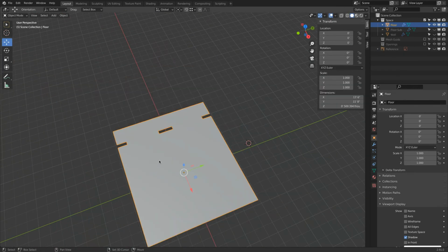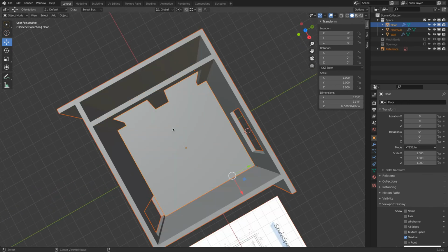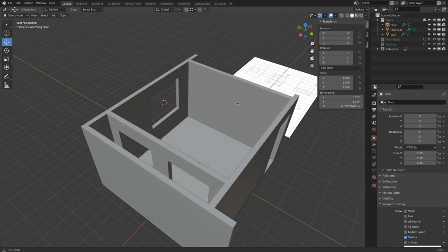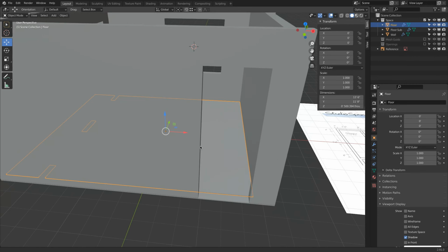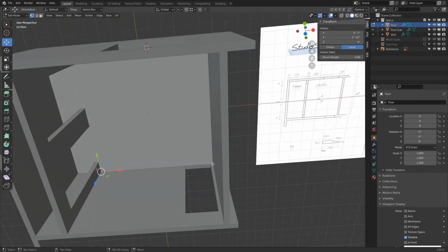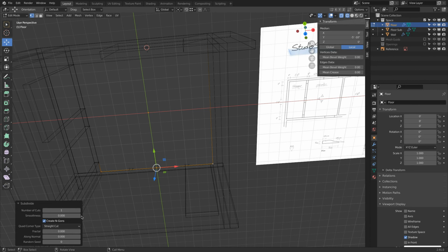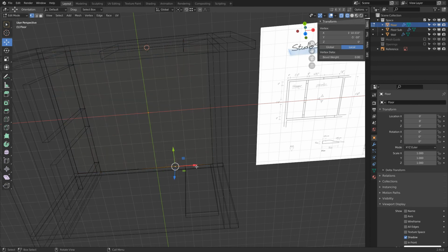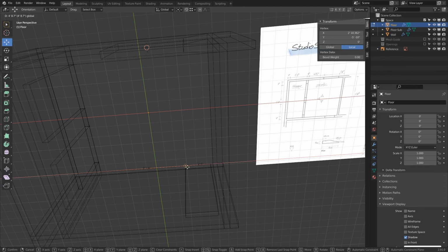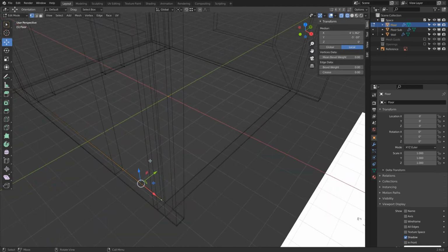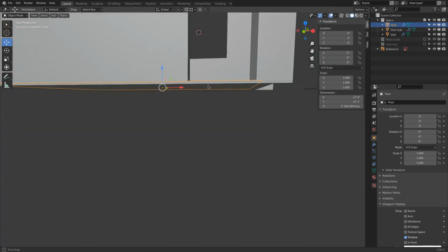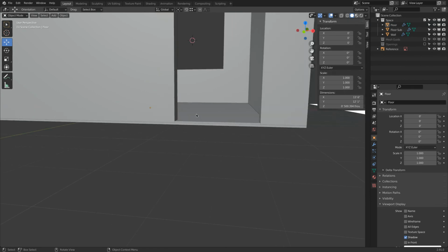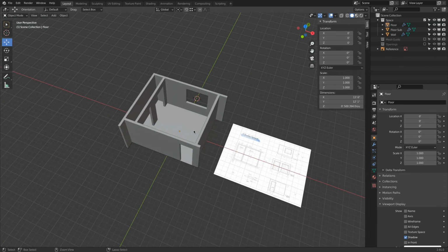Here again, move and snap, move and control snap. There we are. So there we built our hardwood floor as it would flow around the interior walls. And oh, here we forgot this. So right click twice, and then this goes to there, this point goes to there, and these points, to make this more complete, E and Y snap to there. And yeah, that looks good. Okay, ready with this one.